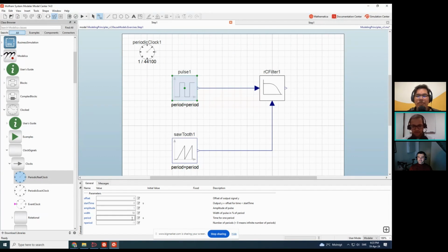Yes, we need a frequency higher than 20, so let's take around 110 hertz. For that, I will set my period as 1 divided over 110. So it's 110 hertz, and we can hear it, right? And then we will set all the other values as default, right, Leo? Yes. Okay, fine. So that's the only thing we change here, the period as 1 over 110, which represents 110 hertz.